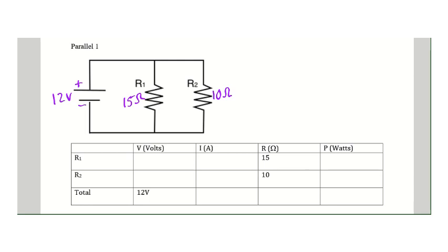The current comes out of the power supply. Everything's fine. Coming along, and we get to this point here. What do we have? A choice. You can go through resistor 1, or you can go through resistor 2. Because you have that choice, this is considered a parallel circuit.